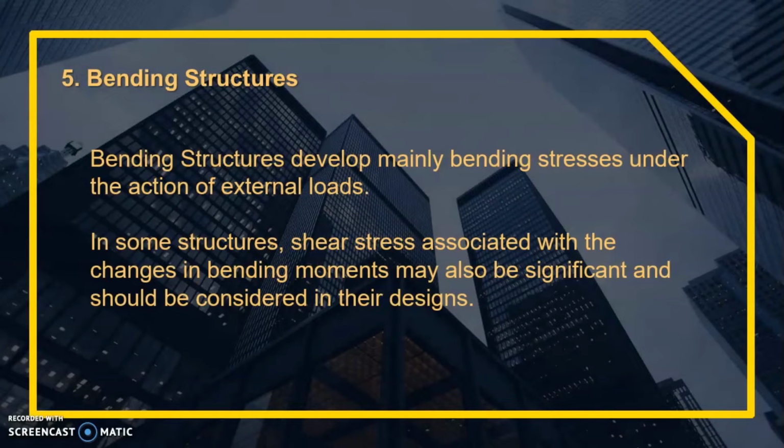Number 5 is bending structures. Bending structures develop mainly bending stresses under the action of external loads. In some structures, shear stress associated with the changes in bending moments may also be significant and should be considered in their designs. Actually, palaging magkasama yan. Pag may bending tayo sa horizontal structures natin, palaging may kasama na shear.